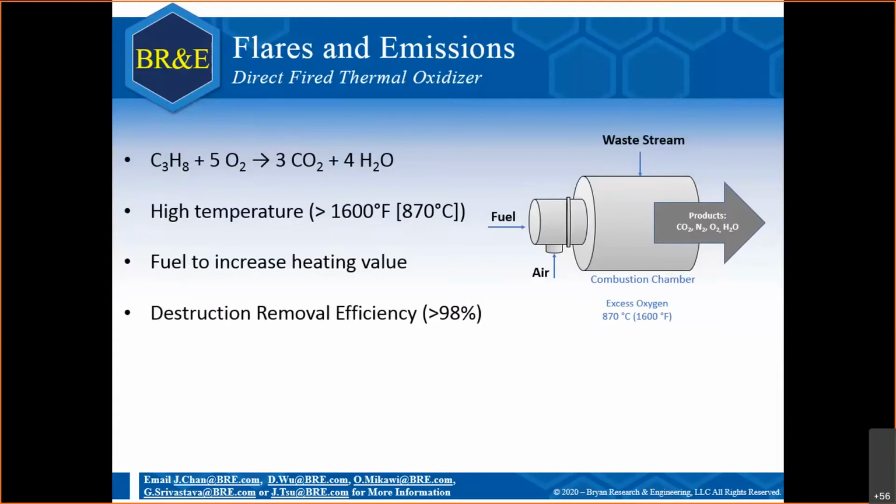The EPA actually allows companies to assume a 98% destruction of the chemical species if the manufacturer efficiency is not available. Incineration can yield a number of different species. The exact quantity and relative amount of each depends on your feed composition and also your combustion temperature. As mentioned earlier, the complete combustion of your carbon species will yield CO2 and H2O.